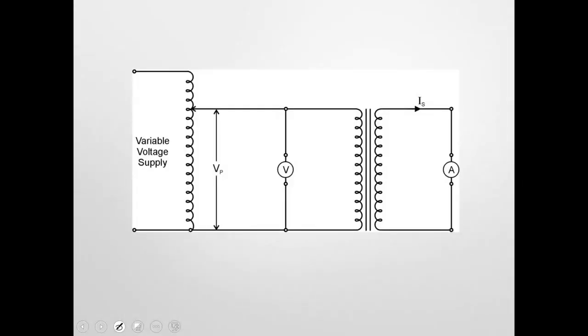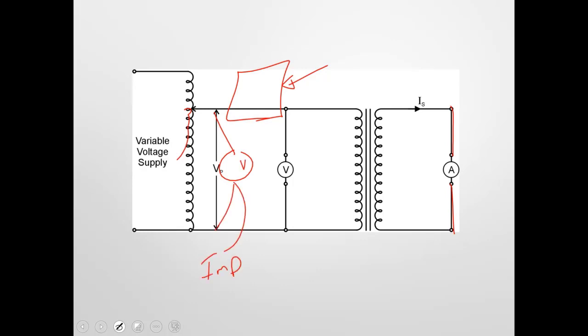Okay, here's a little diagram of that topic. We have a variable voltage supply and a shorted secondary. Same test, we just removed the watt meter. When you guys come in to do lab here, we're going to do this test all at once. We're going to measure voltage and the watt meter to see what the copper losses are. The voltage from our voltmeter is our impedance voltage, and the watt meter reading is our full load copper losses.